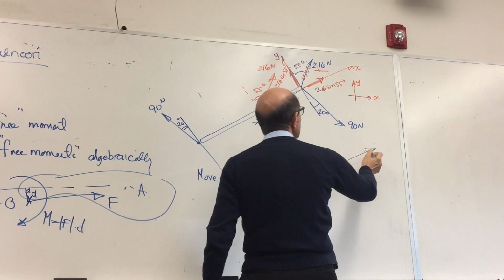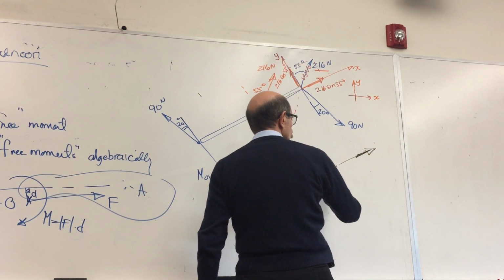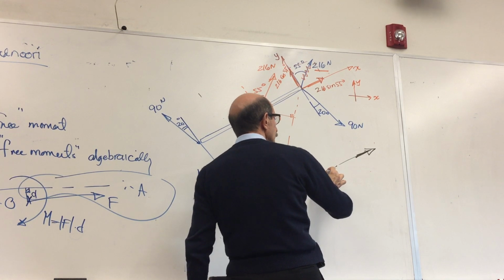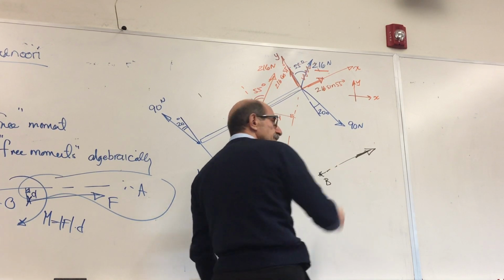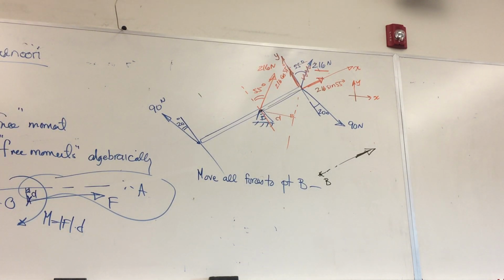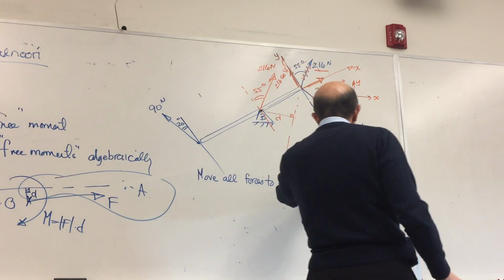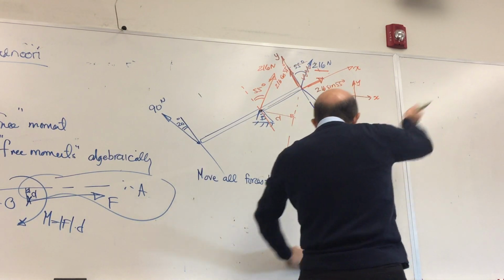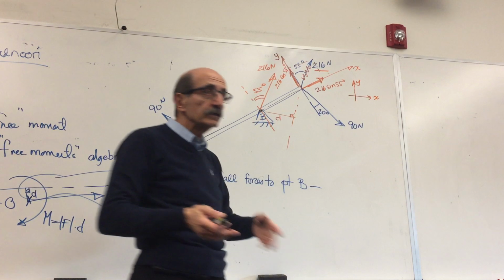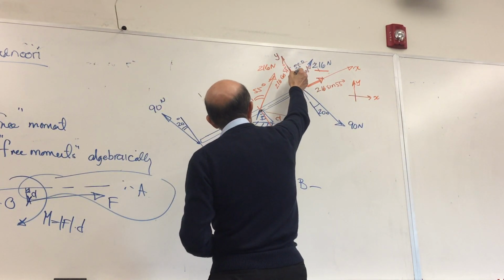This is point B, this is that force, it's passing through that point. So there is no vertical distance from here to this line, because it resides on that line. So the vertical distance is zero. So anytime you take a moment of a force about a point that is along its line of action, that would be zero. So this doesn't generate a moment, only this one does.